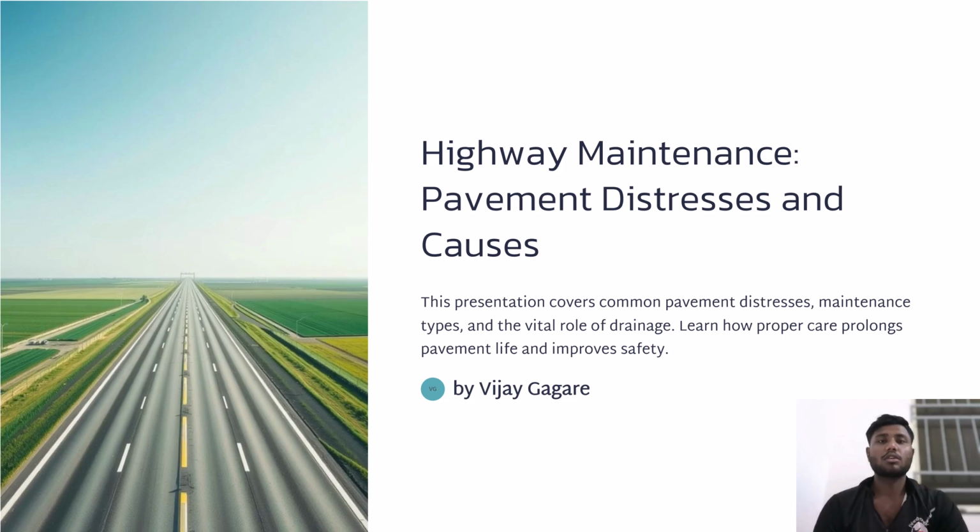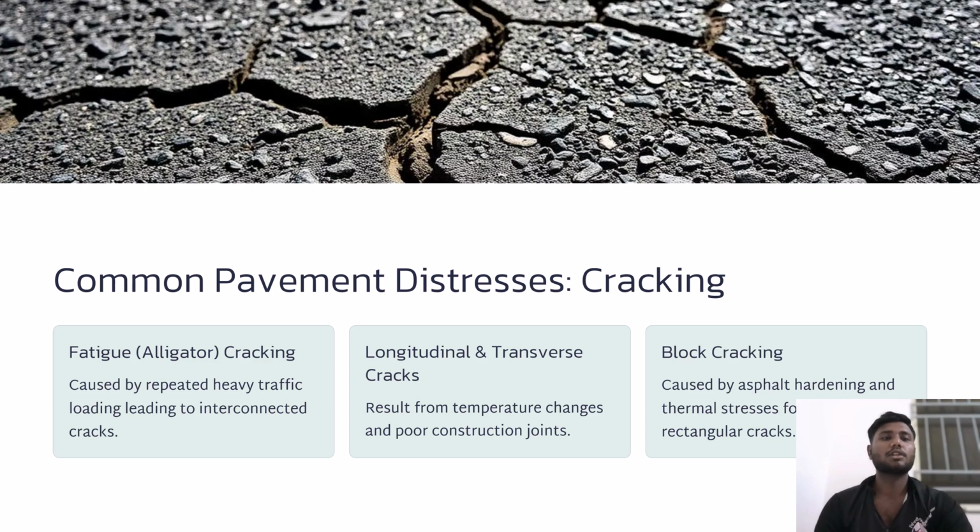Onwards, the first topic is common pavement distresses, cracking. There are many types of cracking. First one is fatigue or alligator cracking, caused by repeated heavy traffic loading, leading to interconnected cracks. Second one is longitudinal and transverse cracks.